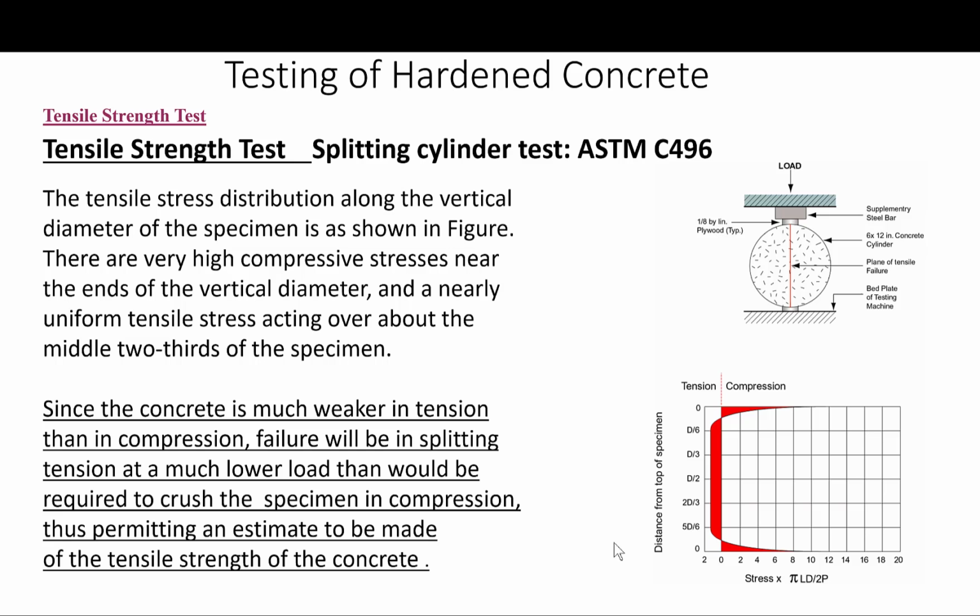It should also be noted that recent, more detailed analysis of the split tension tests have shown that the split tensile strength determined according to these test procedures should not be considered to be a true material property. It's not a true material property. The results obtained depend on the specimen size and the width and type of the bearing strips. So it's not really a true material property because it depends on so many variables. So that's the split cylinder test.